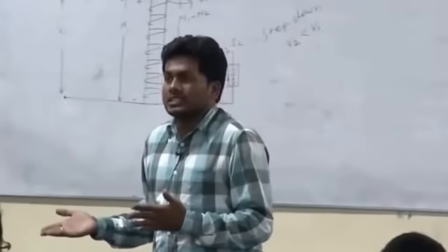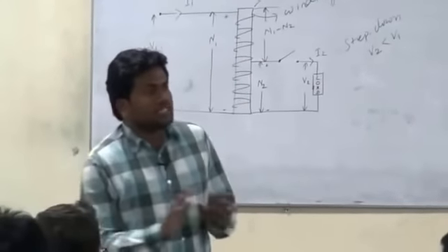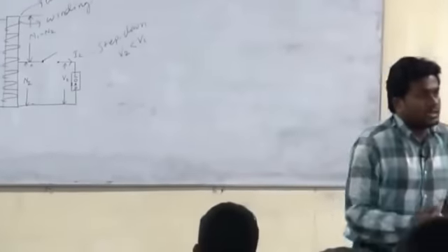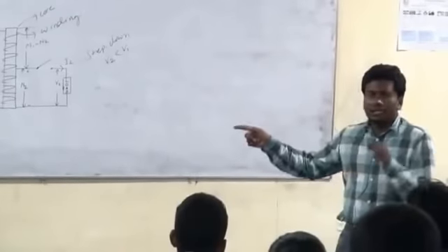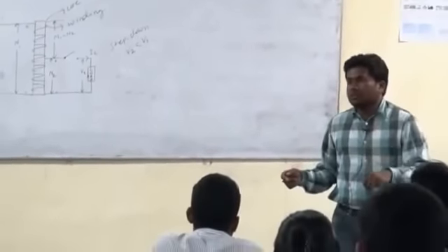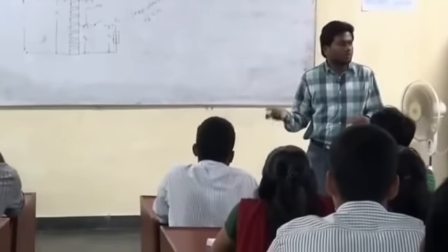Whereas in a resistance potential divider, we can simply change the voltage. We cannot play with the current value. But in a transformer, if voltage is less, then obviously current will be more. If voltage is more, then current will be less, in the secondary and primary both.